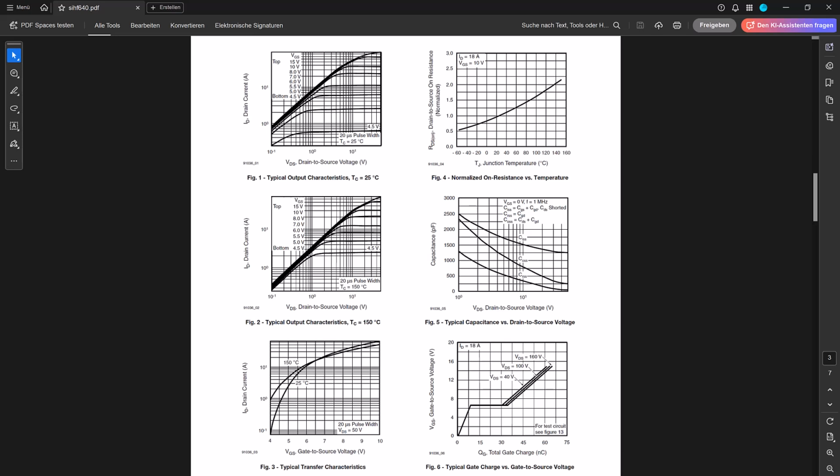What does it tell you? Two clearly different regimes. On the left, the curves are nearly vertical, the triode region, where the MOSFET behaves like a voltage-controlled resistor. On the right, the curves flatten out, the saturation region, where the current depends almost entirely on VGS, not on VDS. This is the fundamental DC map of the device, and we'll study it in Lesson 3.